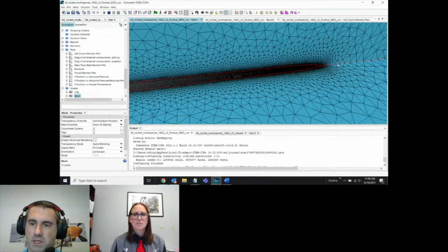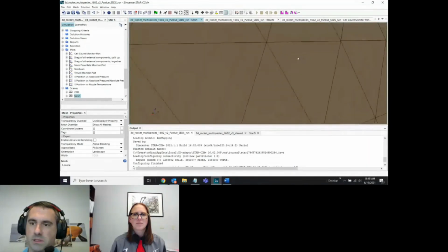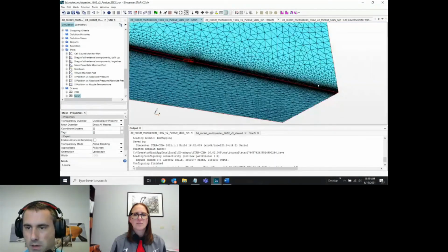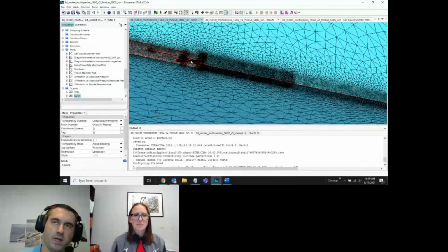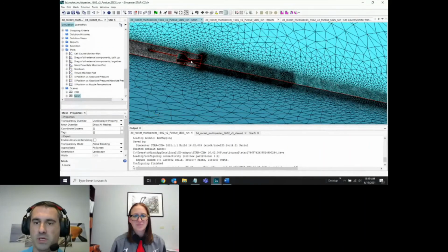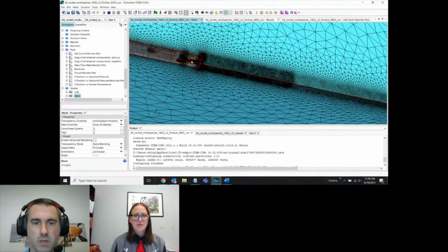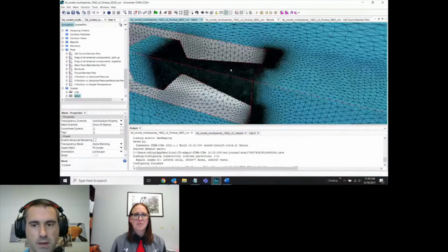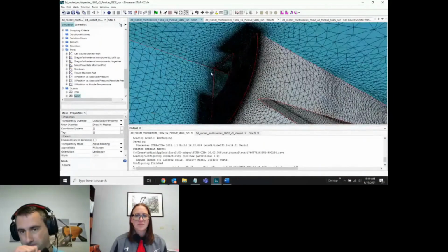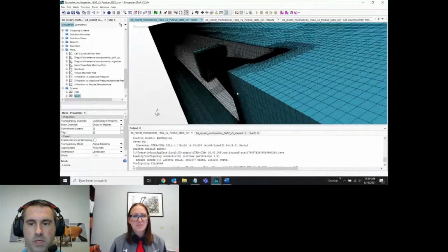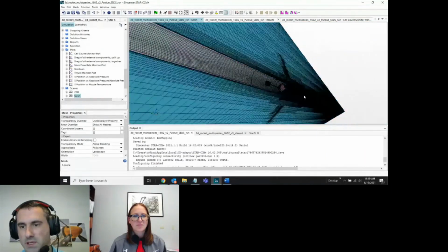So in other words, you can see how this is smaller. This is much bigger out here. This surfacing in here is much smaller. And you'll see those same sorts of behaviors in the volume mesh because I'm not going to get into detail here, but this is a pre-step that's needed to then go in and produce the volume mesh. So same here. So you can see all that small refinement. So anyways, after this, you have the actual volume mesh, right? So you can see that same sort of sizing.